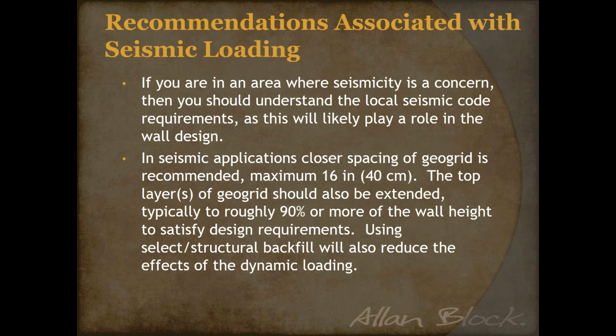And then next, the second portion of this presentation is talking about seismic activity. Seismic activity should be important for anyone to consider that's in a high seismic zone, whether it be for a tall wall or a short wall. Our rule of thumb is if a wall is under 6 feet in height, oftentimes we don't necessarily run seismic analyses, but that's really up to you again.